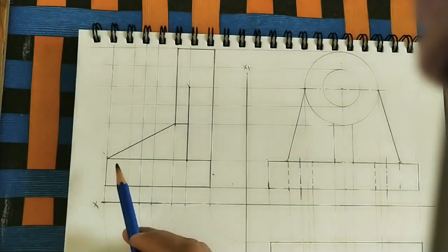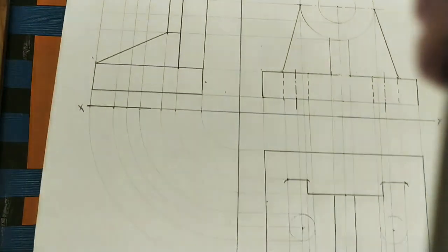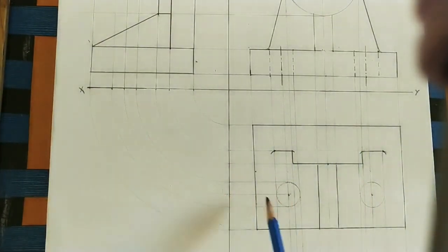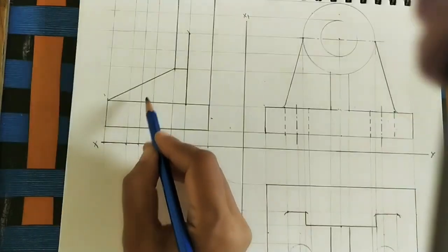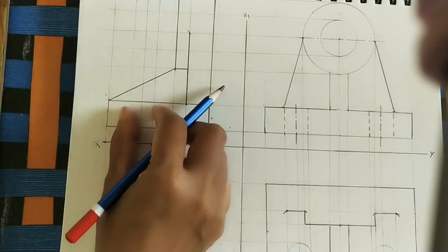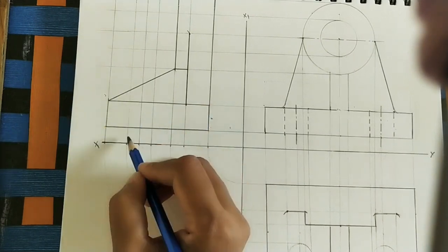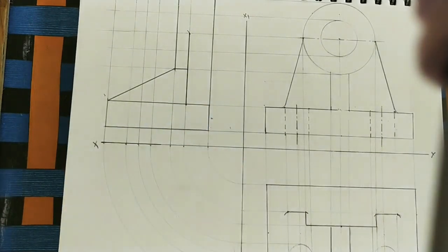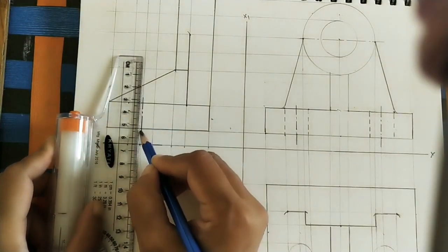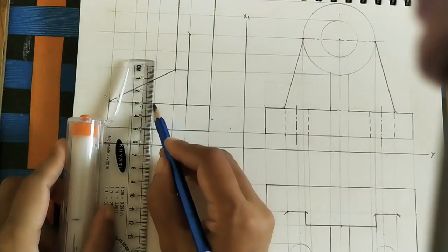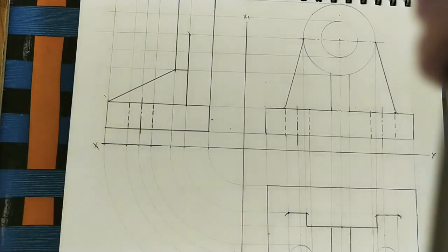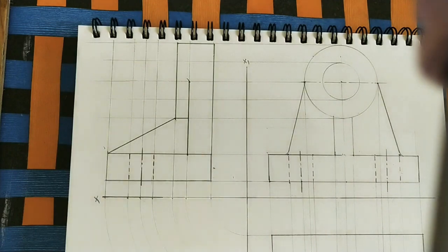So we have to take the dimensions from these circles. Already we took the projector lines from the circles. These are the hole projector lines. Here we have to show the circular hole. It is invisible, that's why dotted lines. These two are dotted lines. This is the axis line. Let us do it here. Two long lines with a dot, and make this line dotted, invisible lines. This is the circular hole. It is invisible. So this is the complete side view.